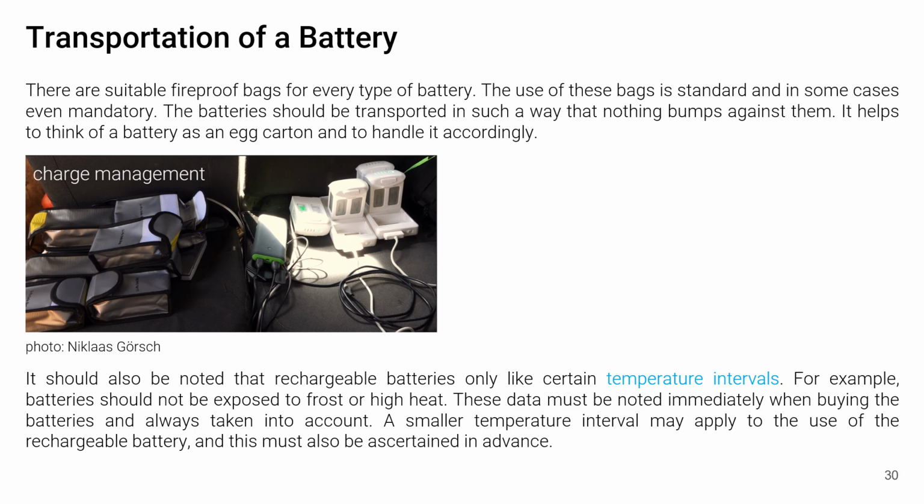There are suitable fireproof bags for every type of battery. The use of these bags is standard and in some cases even mandatory. The batteries should be transported in such a way that nothing bumps against them. Here it helps to imagine a battery as an egg carton and to handle it accordingly.